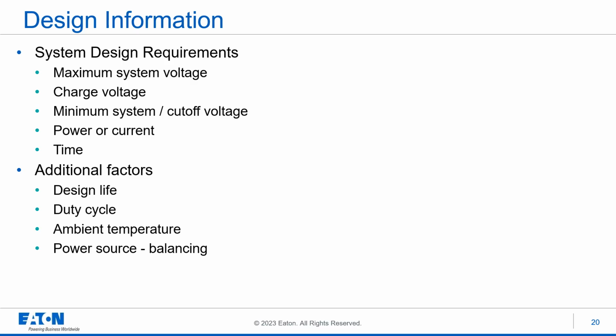You might also have a maximum voltage to meet the above operating voltage. This might be due to the possibility of an overvoltage condition. I've seen this most often in automotive applications where they must account for a load dump occurrence.